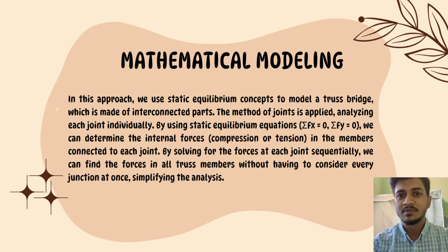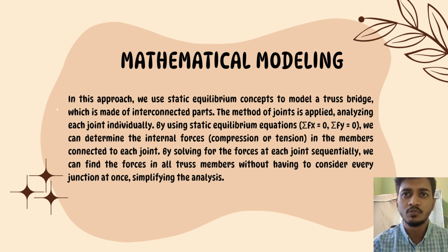Now we can talk about the mathematical modeling of this topic, and we can see on the first slide here that in the mathematical modeling approach we use the static equilibrium concept to model the truss bridge, which is made of connected parts, and then the method of joints is applied, analyzing each joint individually.